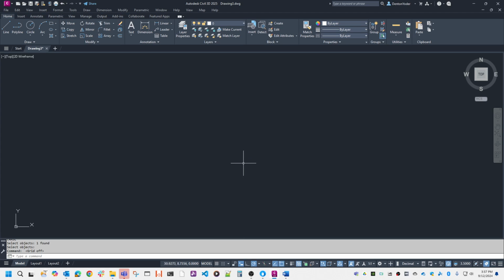There's a lot of them down here. Here's a grid. I'm going to turn that off. We actually could go through and turn about everything off. We don't have to turn everything off, but turning most stuff off would probably help us learn the system better. And we can come back and turn them on as we learn how to use them. We will want to use object snaps. We'll want to use the ortho or the polar. We'll want to use not the isometric, with the polar. We'll want to be using them and getting used to them, and then we can turn them on and use them. Okay.